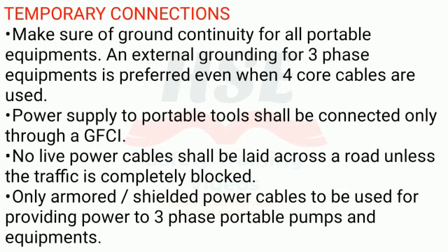An external grounding for three-phase equipments is preferred even when 4-core cables are used. Power supply to portable tools shall be connected only through a GFCI. No live power cable shall be laid across a road unless the traffic is completely blocked. Only armored, shielded power cables to be used for providing power to three-phase portable pumps and equipments.